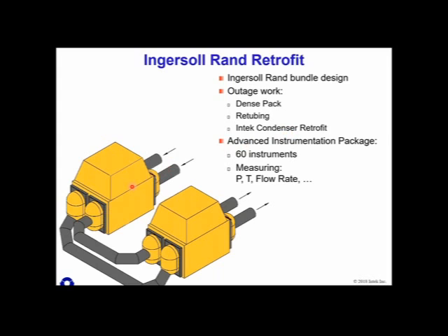They were going through a retubing. They keep their tubes extremely clean. They have a ball cleaning system. They have Admiralty brass tubes. They were going to retube with Admiralty brass. The wall thinning on the tubes was the driver for the retubing effort. They didn't have too many plugged tubes. I think it was around 8%, which was their limit for retubing the unit. But the tubes were kept immaculately clean because of the ball cleaning system and their cooling tower maintenance. Very clean system. But anyway, they were going through retubing. During the work, they were also going to upgrade the turbine.